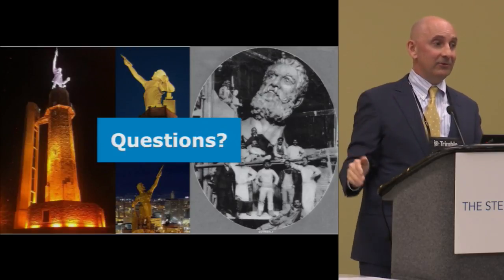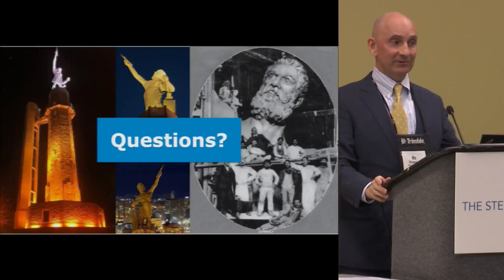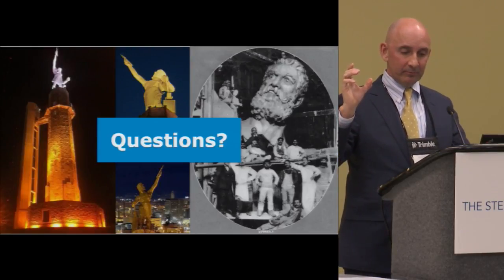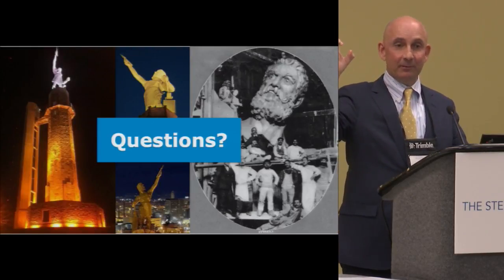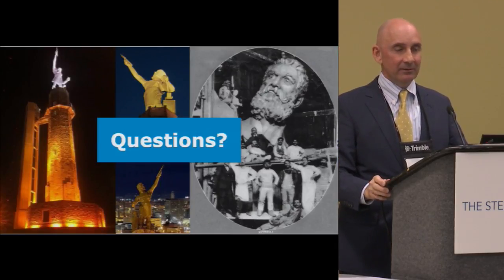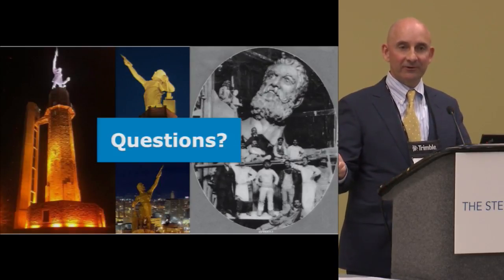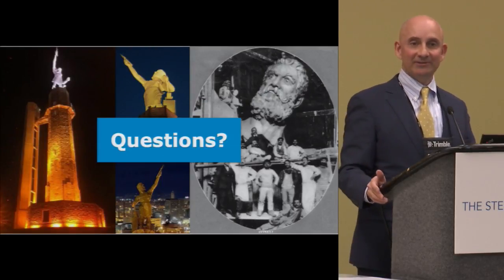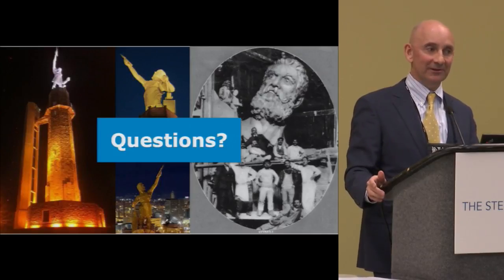But if you did that, then you could use the plastic interaction equations, which have the ratios raised to powers, so you get more strength out of it. Essentially, that is what it does. The axial strength ratio is squared, I believe, in those equations, and the flexural strength, M over Mp, is to the first power. And then if you calculate the shear strength and add it to that too, it's raised to the fourth power for the plastic strength. But you can't use that with stability effects.